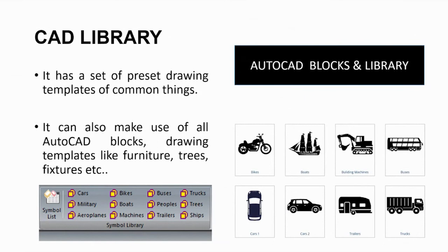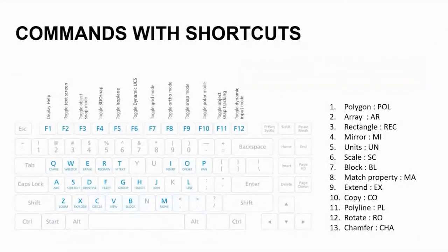It's available in the Back to CAD tab in the CADdirect interface. And all the commands also work in the same way with the same shortcuts. You can see Q for quick save, D for dimension styles, F for fillet, B for block. So all the shortcuts are exactly the same.